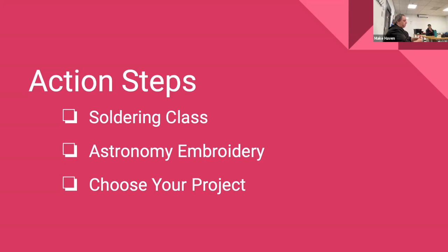Question for you on the surface mount. I was told that with soldering, obviously you're going at it with the soldering tip, but with the surface mount, is it some sort of glue? There are several different approaches for surface mount soldering. One is using a soldering iron. That one was actually done using a soldering iron. Then there are versions where you use solder paste and you cook it in an oven, called a reflow oven.